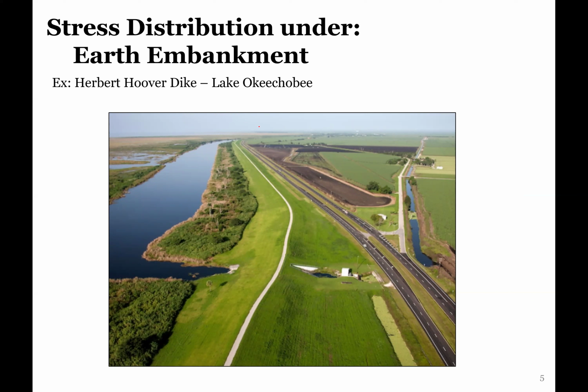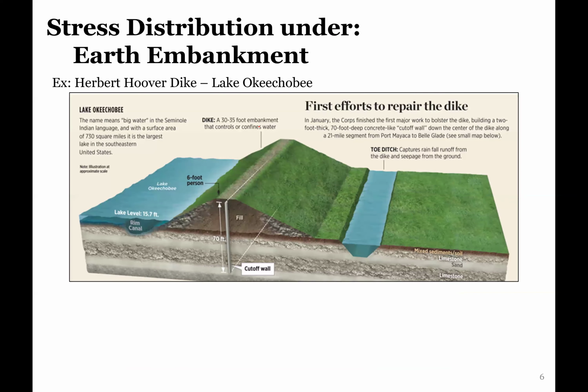So this is really popular for dikes, or like we see at Lake Okeechobee. That looks something like this. And we have this fill material with those cutoff walls, like the seepage thing that we had talked about before. So we need to understand the seepage or the flow rate behind that, but then also the increase of stress. If we had a layer down here, that might have an issue due to that.